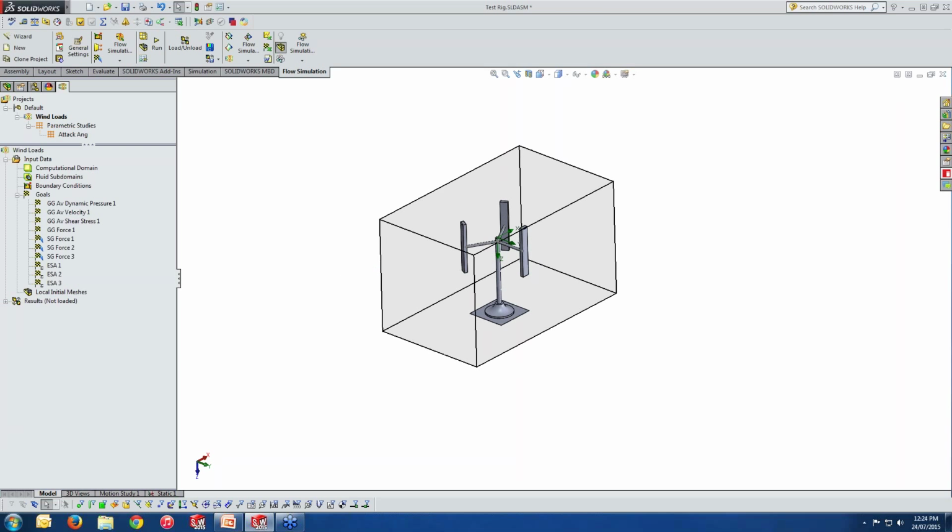Well, this case is simply considered a wind tunnel as we set up, with 12 meters per second in the X plus direction here. What is very important is that we are always trying to achieve an optimized simulation. In this regard, we have to make the software trace some parameters which are very important to calculate very precisely, and also make the mesh resolution suitable. This comes down to a series of goals you are simply defining.